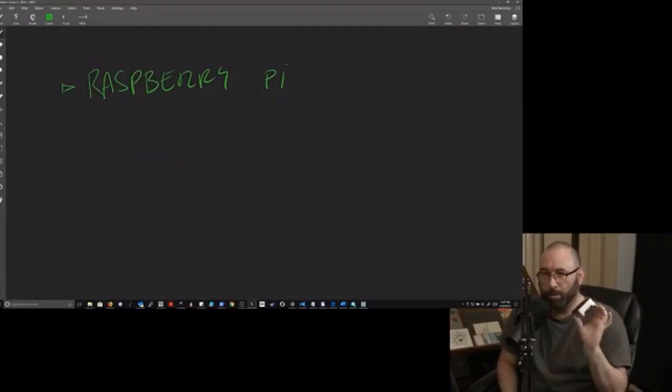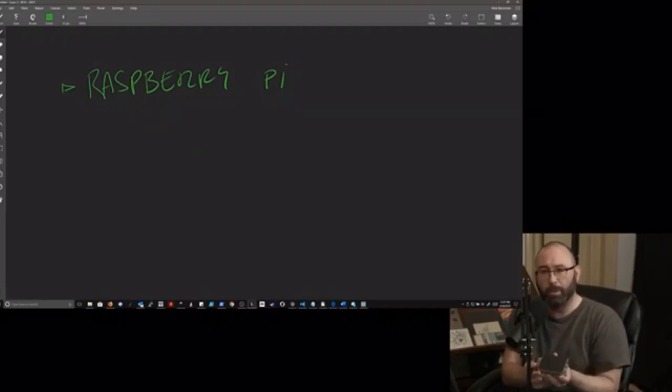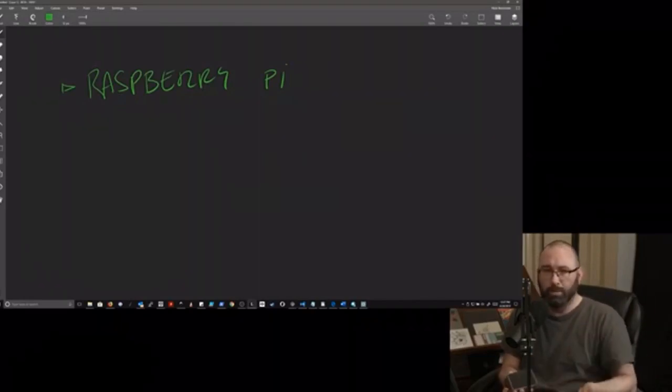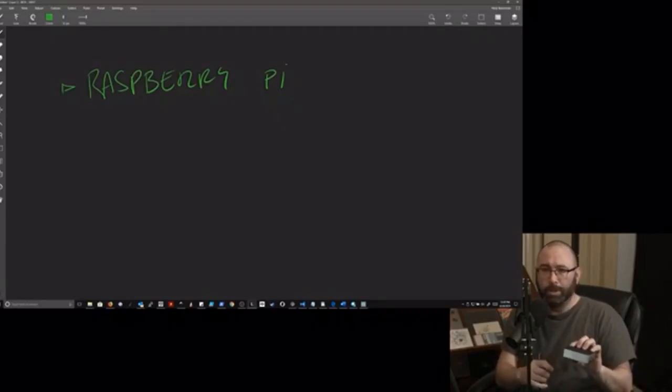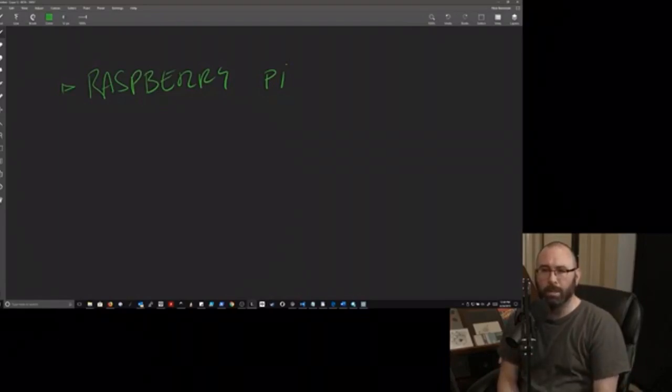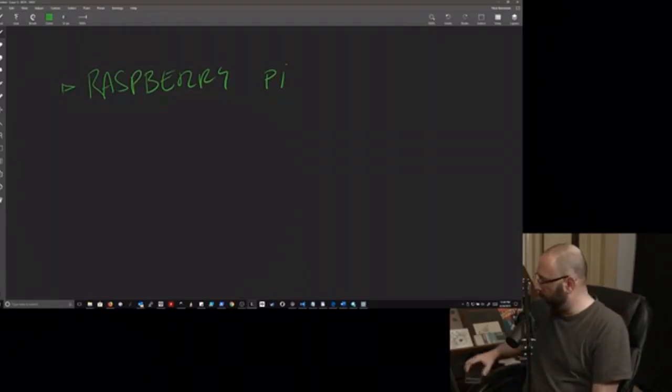The great thing about a Raspberry Pi is they're very small. They're the size of a deck of playing cards, basically. It will come to you with just the motherboard, and you can optionally buy a case for it. For marine use, what I would probably do is stick the board in some Tupperware and put the lid on it, so it's not going to get salt air and corrosion. Then you cut a little hole in the Tupperware, put the cables in, and a little bit of hot glue around them gives you a nice airtight seal, and that should be pretty good for most people.